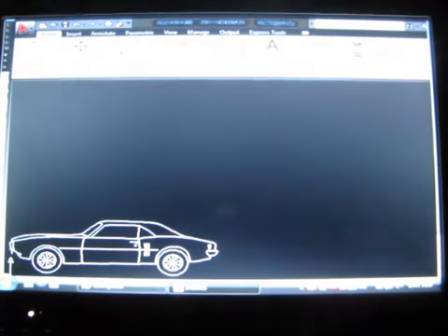In previous sections, we discussed the value of inputting commands with the keyboard. One key to efficiency in AutoCAD is taking advantage of the keyboard shortcuts, the function keys, and command aliases. The function keys act as toggles. They turn certain drawing aids on and off. The two you're going to find that you will use the most are the F3 and the F8 keys.